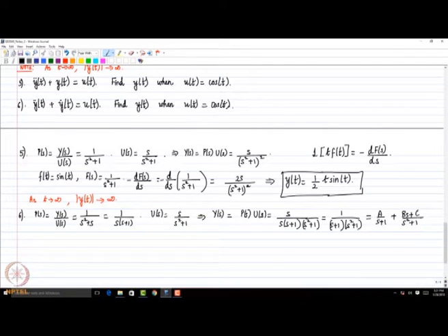Pole is a characteristic of the system or the plant. Here the cancellation of s was a mathematical operation which came in due to the specific nature of the input that we have. But in general, we have a more subtle idea which is called pole zero cancellation. We will come there when we go deeper into control system design. Pole zero cancellation is an important concept, but here it is not so.